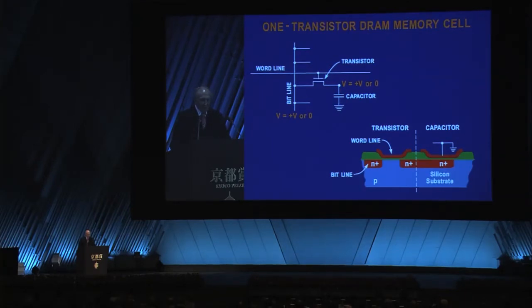I kept working on various configurations for a few weeks until I finally realized that the stored charge could be read back out through the same transistor through which it was written, which would create a small detectable signal on the bit line. The cell had been reduced to a single transistor and a capacitor at the intersection of two access lines. I was satisfied that this was as close to my goal as possible and offered a great reduction in complexity compared to the 6-transistor memory cell.